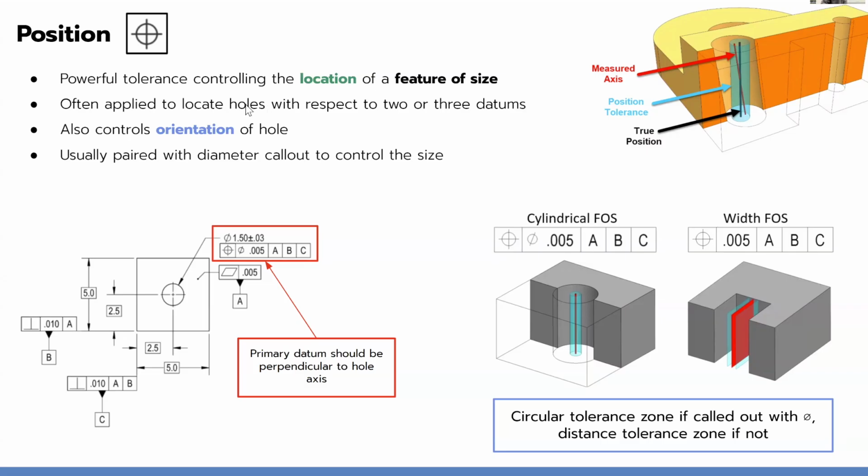So something like this is actually a problem that's popping up with the drivetrain drawings for our chassis. If you guys know, this is a bit of an example. We're already controlling the position of those holes, but it was requested that we also control the perpendicularity, right? So now it's a question of is the perpendicularity control overkill or is the position just enough?